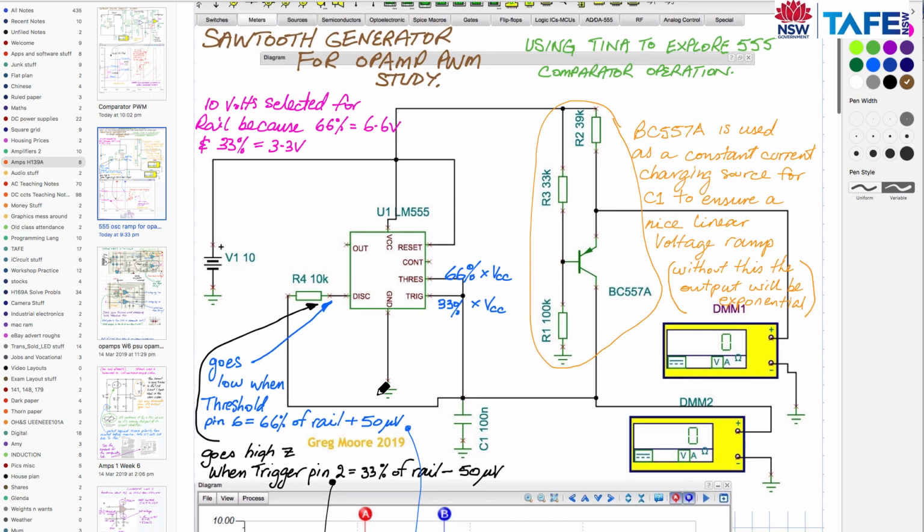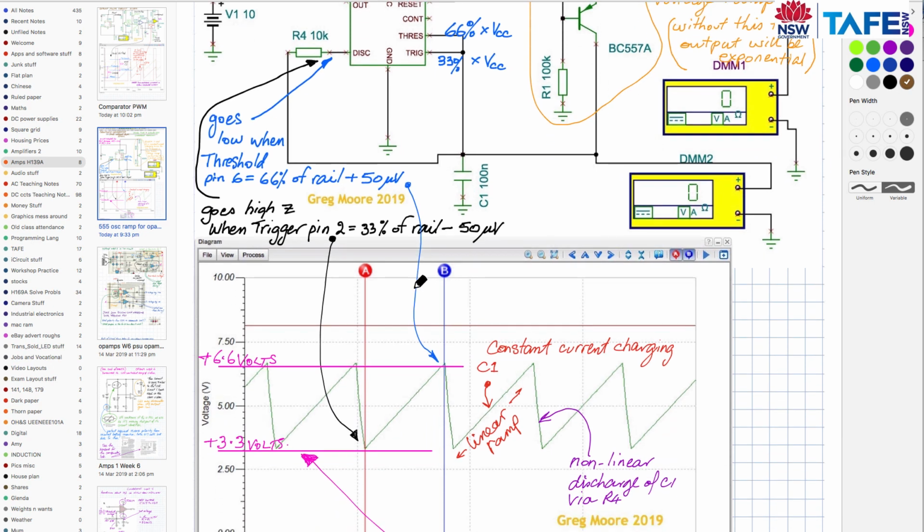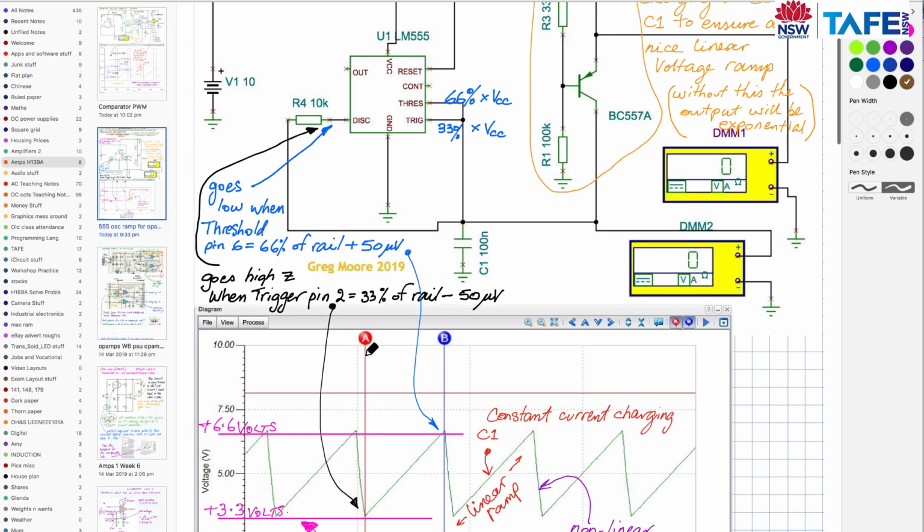And these ramp generators, sawtooth generators if you like, are used in many, many types of electronic equipment. I remember working with radar and oscilloscope circuits many years before, and dealing with some beautiful circuits set up for sawtooth waveforms. Even the deflection in CRT type televisions had to use a sawtooth waveform like this to get linear deflection on the screen.